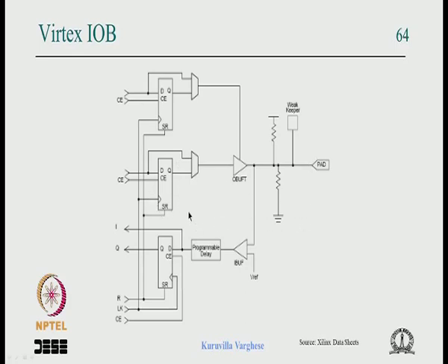So that's a good idea, because otherwise if it is already coming through some combination circuit, there will be a lot of delay from the clock edge, and as it goes out of the chip, it can suffer further delays. So it will be useful to synchronize it with the clock, because it appears with minimum delay after the clock. Then maybe it can be resynchronized at the receiving end, or go through some combination circuit and get resynchronized.